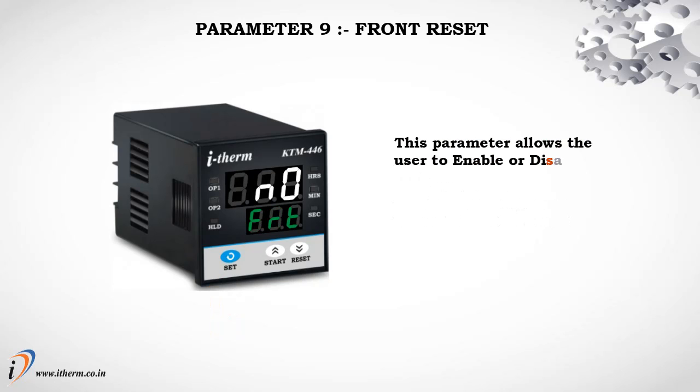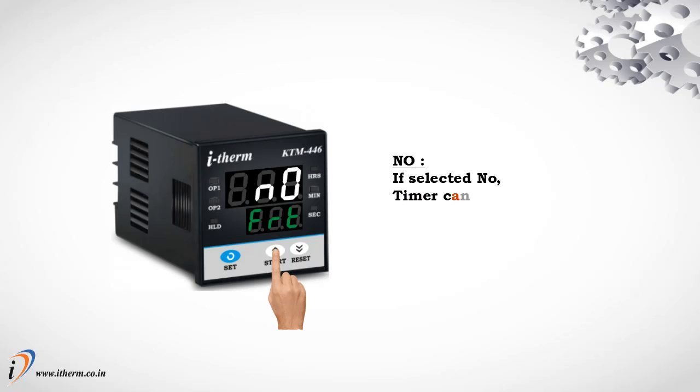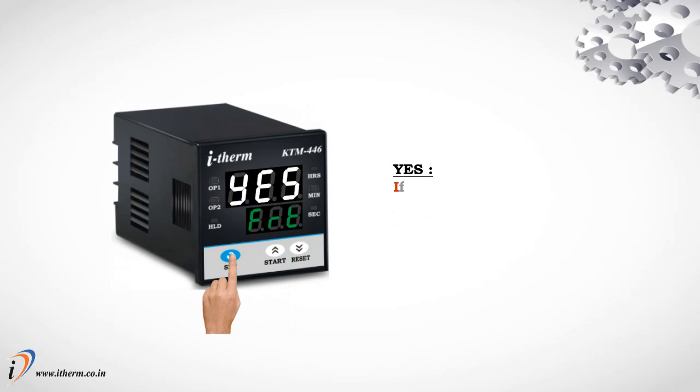Parameter 9, front reset. This parameter allows the user to enable or disable front reset function via front key. This feature prevents unauthorized attempt to reset the timer during run mode. If selected no, timer cannot be reset through front panel. If selected yes, timer can be reset through front panel.